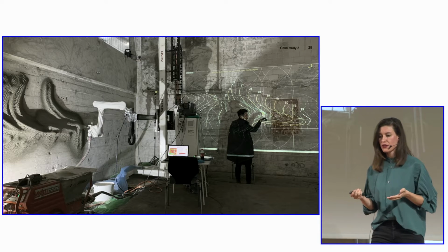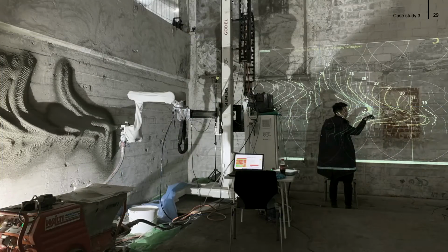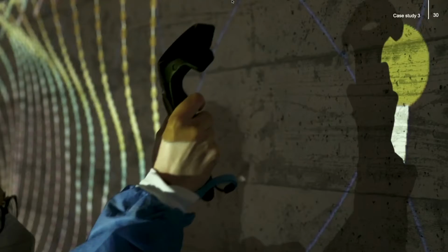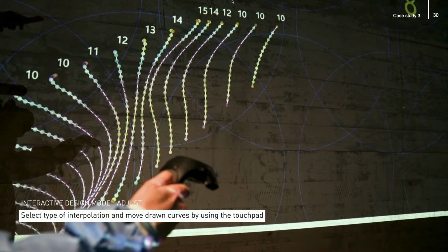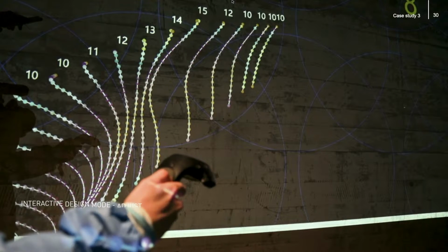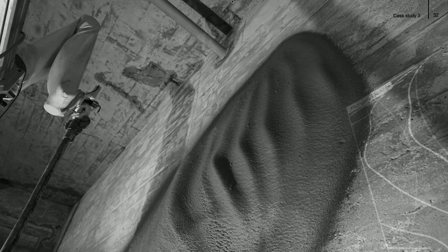The research combined 3 parts: an interactive design setup, an augmented reality setup, and a robotic plastering setup. It utilized a controller-based interaction system to enable humans to interactively design and fabricate articulated plasterwork in situ, taking the building structure and the as-built state of the construction site into consideration. The design workflow of IROB allowed humans to generate complex digital models in minutes and rapidly generate multiple design alternatives. It further allowed humans, with very limited programming skills, to instruct a robot by demonstration.